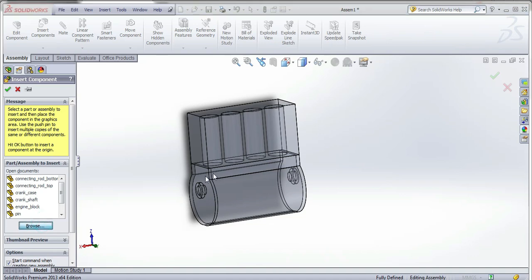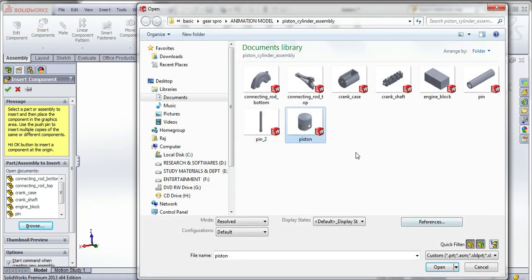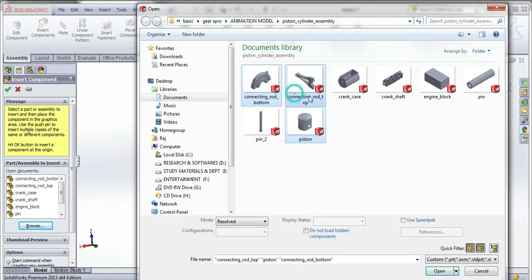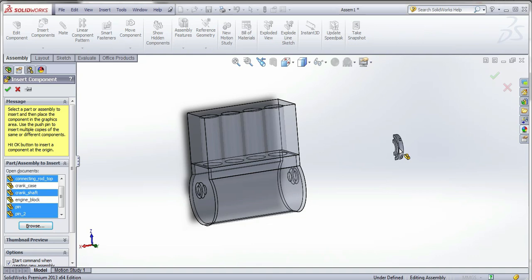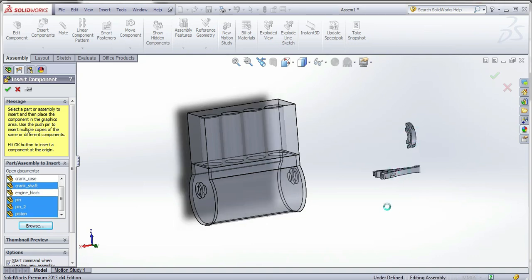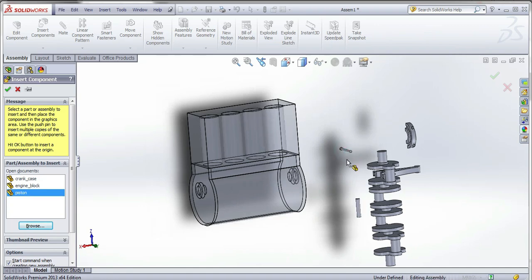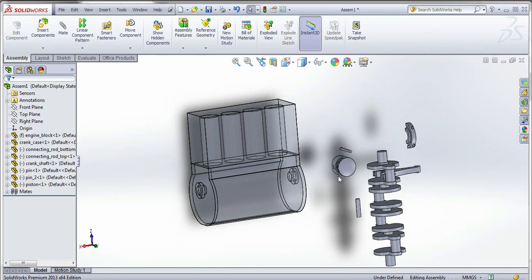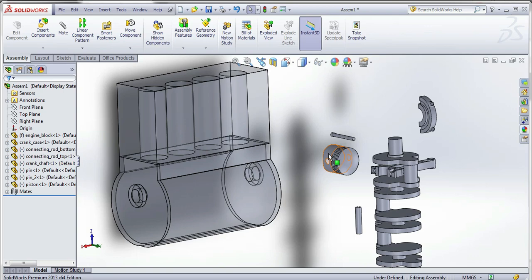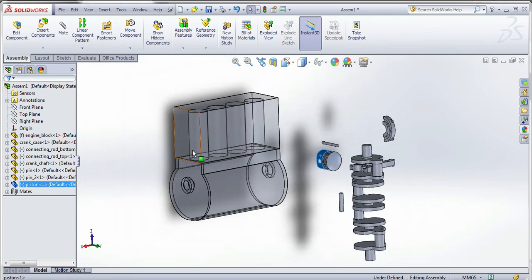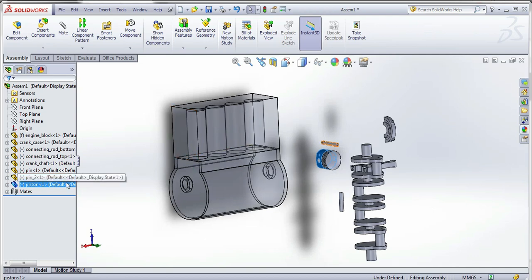transparent view. Select the piston, connecting rod and crankshaft, pin, everything. First one, second one, just for a click, one by one. This cylinder surface first to hide any one of the component. Bottom component we can first to hide. Crankcase to be hide.